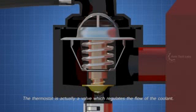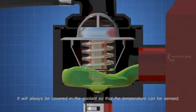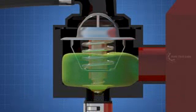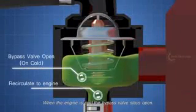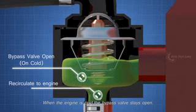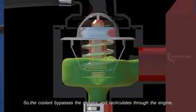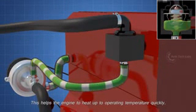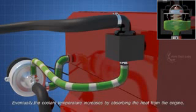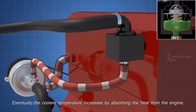The thermostat is actually a valve, which regulates the flow of the coolant. It will always be covered in the coolant, so that the temperature can be sensed. Let's start the operation from a cold engine. When the engine is cold, the bypass valve stays open. So, the coolant bypasses the radiator and recirculates through the engine. This helps the engine to heat up to operating temperature quickly. Eventually, the coolant temperature increases by absorbing the heat from the engine.